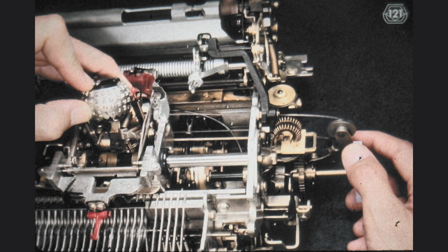We simply rotate the element counterclockwise 3½ turns from the position indicated here, and then lock the spring tension into position by half-cycling a character, so that the rotate detent can engage with the skirt of the type element. Before you half-cycle a character, however, make sure that you have the T-shaped slot in the rotate pulley facing the front of the machine, where you can readily see it and get at it.